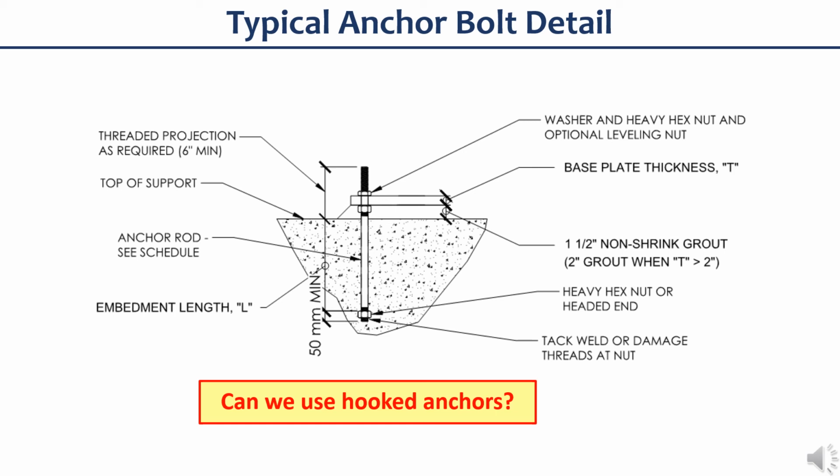Now, a hook is generally not capable of developing the required tensile strength of the anchors. So, as a rule of thumb, we have to use hooks when the tension in the anchor bolt is relatively small.